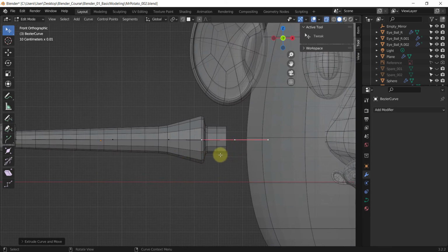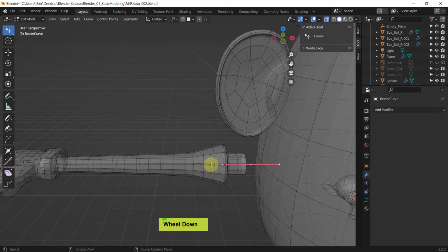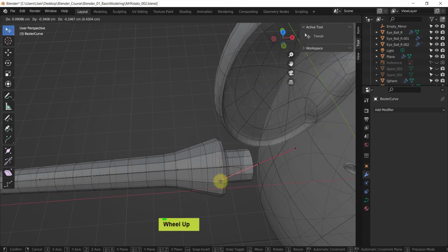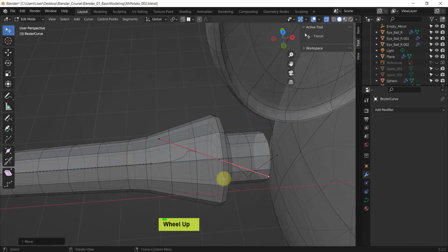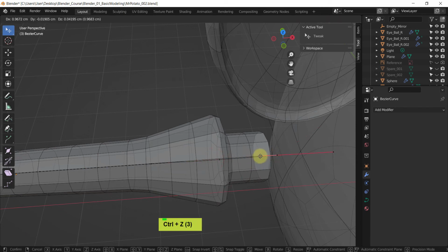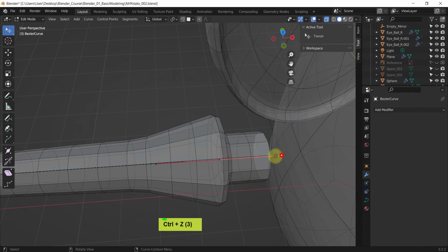Now, something is off. We have to take care of that. The handles are usually too strong, you can see, and that means when you do something like this, and here's another point, these are overlapping. Can you see how the curve goes? It's just off. So before we make any crazy adjustments, what we will do is just reduce the length of these handles.